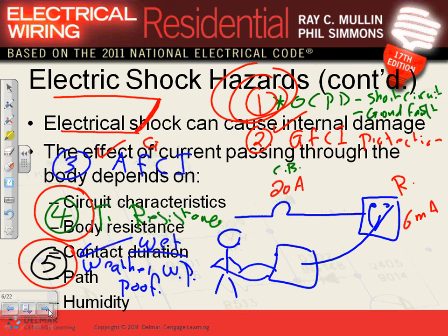Any question about these 5 protections that you need for most of the receptacles and the outlets in every residential? Yes, Dustin? I have a question about GFCI protection. Okay. Let's just say in your kitchen, countertops, if you put a GFCI breaker on that receptacle instead of a GFCI receptacle, is that legit? No problem. You can have all regular tamper resistant receptacles or whatever, with a GFCI circuit breaker. Yep, that's okay. Did you see any inspector? You might, yeah.